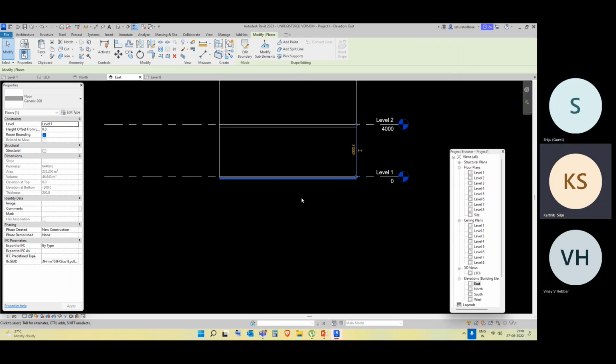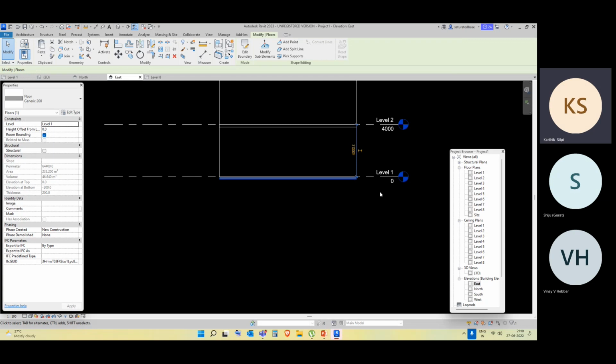I'll just tell. Structural slab level is something like, you have done only the slab, right? Then it is called structural slab level. And slab level is something where you have done the finish for the slab, and also you have laid your tiles or something like that, whatever comes upon the slab. The last level is finished floor level. That level you will only calculate once your carpet layer also is finished.